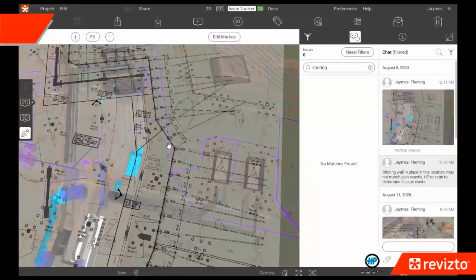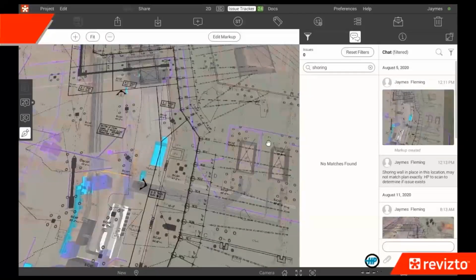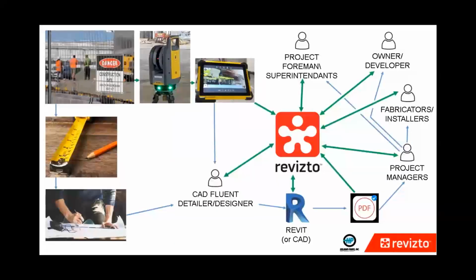One, the plumbing's clipping it a little bit. It's an easy adjustment if it's really there, but that shoring wall going through that big bank of conduit would be a big deal, because that would move all that conduit out into our plumbing, so it'd require a lot of reroute. So we basically have to figure out where that shoring really is out there. And we could use a tape measure and sketch out what's there if we can't get a document.